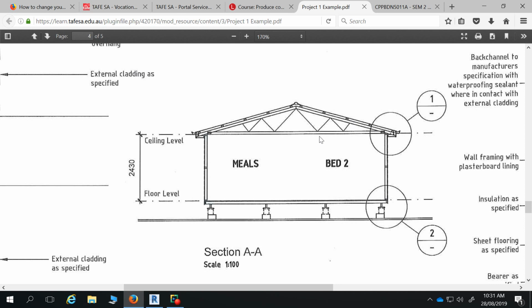Okay, so the bottom chord can just be a detail line offset from the top of our ceiling. So when we put the ceiling in, detail line, that one's a detail line offset at 70. You can do a 90 if you wanted. If you're using 90 thickness, we've changed this roof to a 90 thick, and then we're going to have that roof sheeting offset at the 45 distance. So you end up with those layers, and then, as I said, that top roof sheeting that we've made 16 mil, we just edit the boundaries on the outside so that they come out to the gutter, so they just overshoot the gutter.